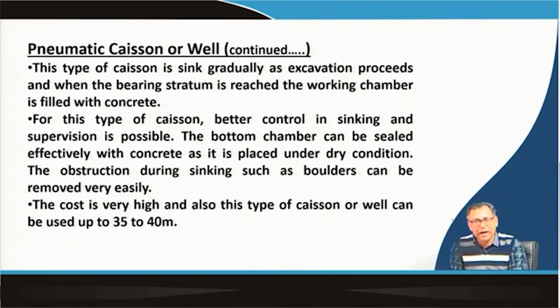But the disadvantages are that this is a very costly method, and this type of well can be used only up to 30 to 40 meter. Okay. And the open caisson can be used for greater depth, even for more than 40 meter.